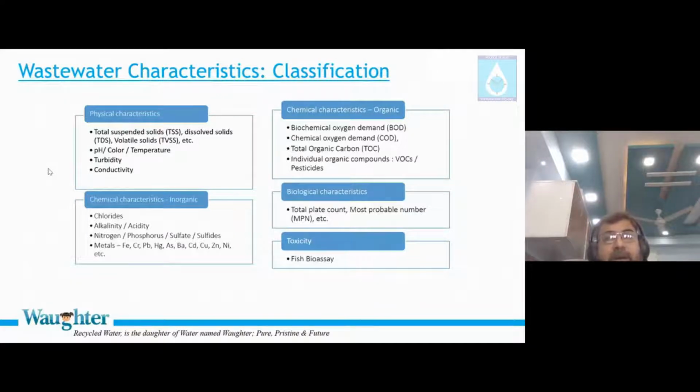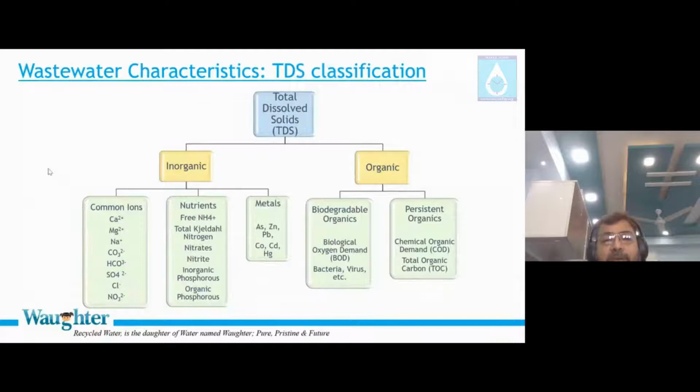See, if you remember my treatment slides, I always talk, technology must be for people and environment. Technology is not a medal that I have got my beautiful technology in the plant, right? As long as things are doing their job. The fish bioassay, which is the most ignored thing in any wastewater treatment facility, is actually a very important way to know the performance of your wastewater treatment plants. Moving further, let's go into a little bit more details.